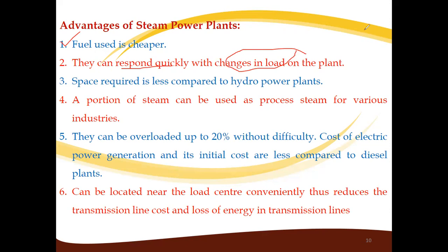Now electricity is not used constantly by customers, so supply and demand can be different for different conditions. So if you see, in daytime the demand is less, and in the morning 6 to 8, or in the evening, we have more requirement of energy. So this power plant responds quickly to change in the load. Next, space requirement is less as compared to a hydroelectric power plant for this steam power plant.